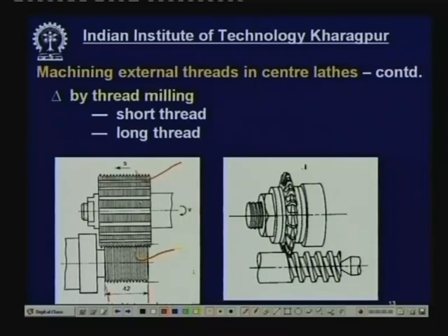The cutting tool is made of a rod of harder material having annular ribs or grooves. These are not helical, this is straight annular grooves, and the threads are exactly similar to the threads to be obtained. Now, this tool, which will be rotating at high speed, will be mounted on an attachment, and this attachment will have a motor to drive it, and the entire thing will be mounted on the lathe bed.